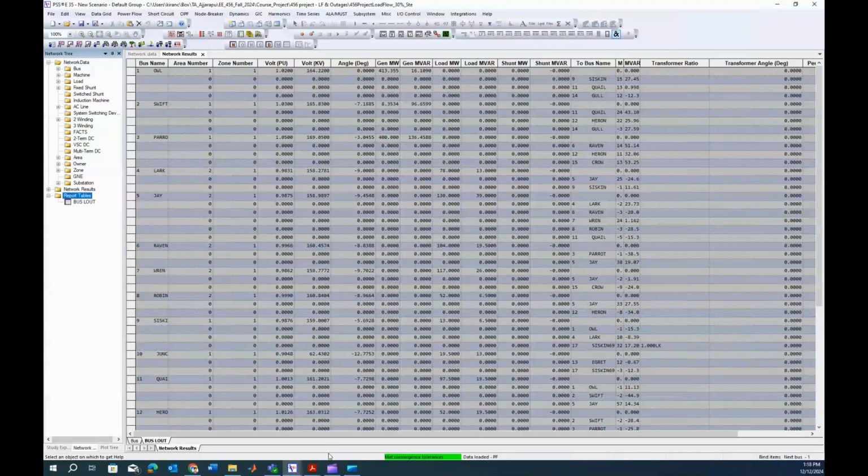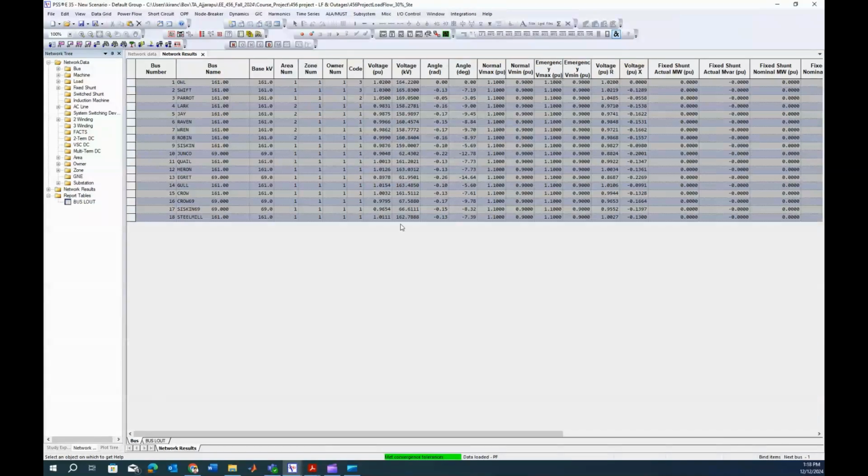And accordingly, you also have certain extra cases to run based on changing the load conditions, where you can modify the loads on the system and also run the load flow, and you can also trip certain lines and see how that contingency is impacting your system and certain other cases. That's how PSSE power flow can be solved using our network that we have.